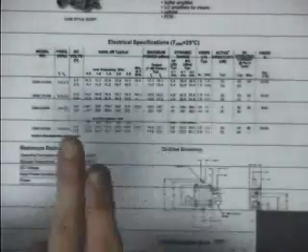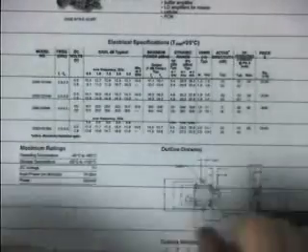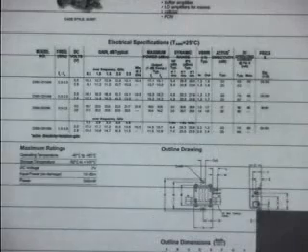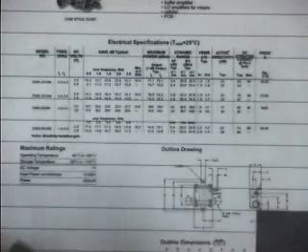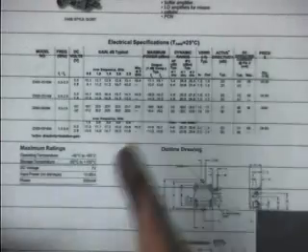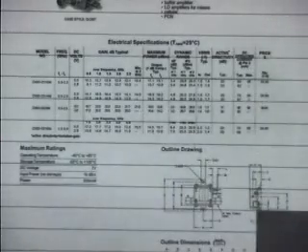Then you multiply by Boltzmann's constant and the bandwidth of your system to get the watts of noise power. Then you could track the carrier to noise ratio, and then when you get down to baseband, signal to noise ratio through your system.